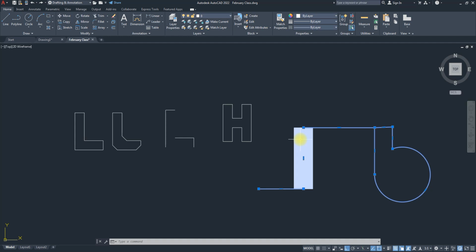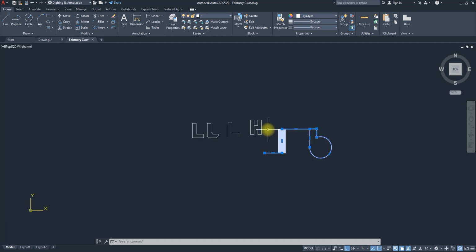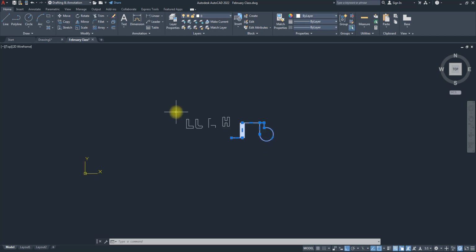All right, so that's that. Remember, what's the shortcut for line again? What's the shortcut for polyline? PL. All right. What's the shortcut for putting on our snap? F9. What's the shortcut for bringing up our grid? F7. What's the shortcut for auto mode? What's the shortcut for dynamic input? What's the shortcut for unit? All right, so we have that.